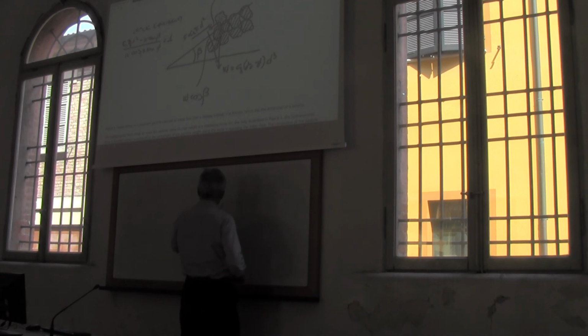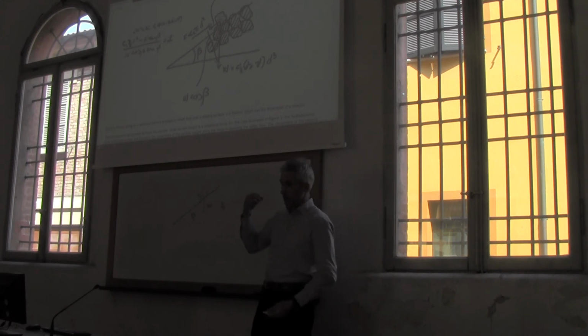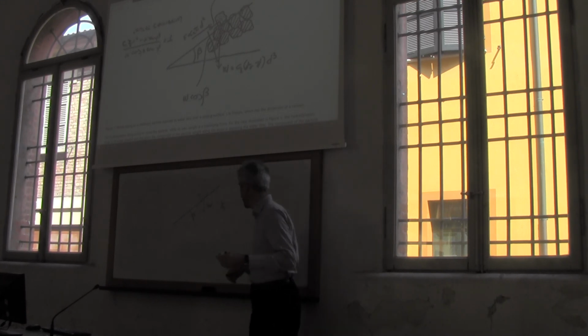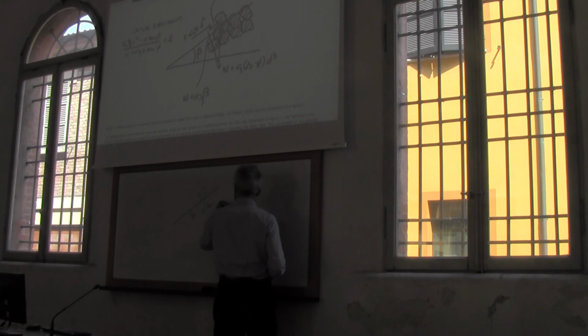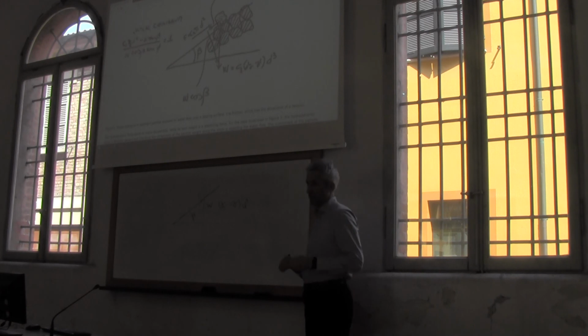Okay, W is equal to gamma S. What is gamma S? It's the specific weight of the armor. So if it's a boulder, it's about 2.6 tons per cubic meter, minus the specific weight of water. Then let's multiply it by a characteristic dimension squared.